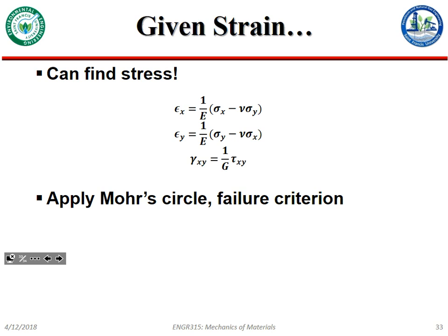There's a group up in Boston, and they instrument a 40-meter long blade with hundreds of strain gauges all over the thing. And they're essentially just working these equations to see where the thing fails, what loads it fails at, what stresses are present, all that kind of thing. Just understanding what's going on in the material.